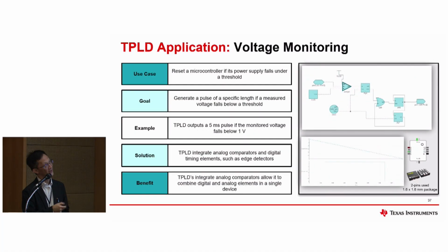Okay, and another one will be what I call voltage monitoring. I think you will be very puzzled why you need to use a PLD, right? You can actually go off the market and just buy a simple SVS, TPS3809, that can do the job. The good thing about this is that we are able to provide you more integration, right? We have integrated the analog comparator, digital element, and also the ESD detector. All right. So this is another usage as a voltage monitor.